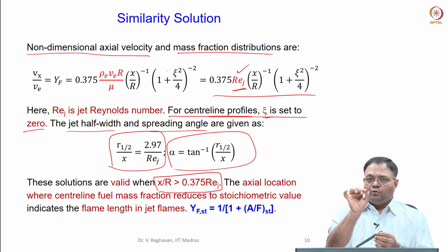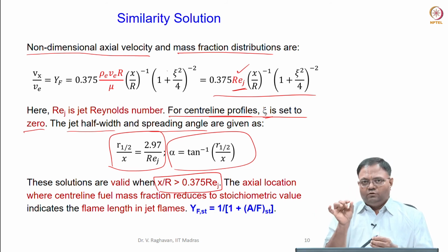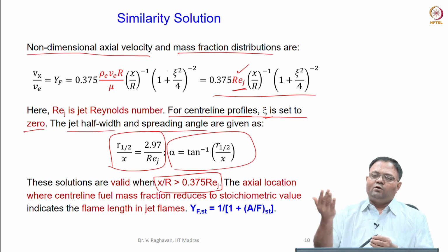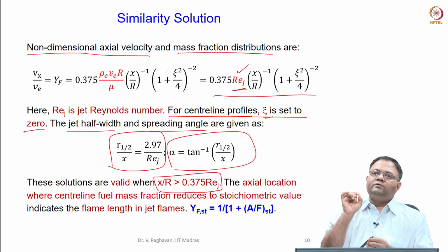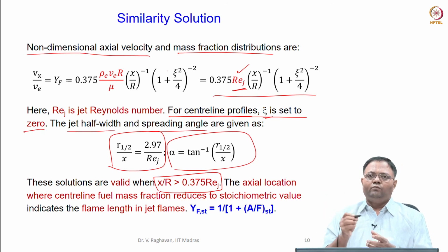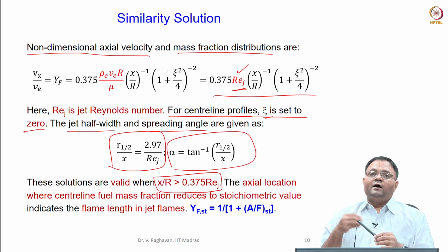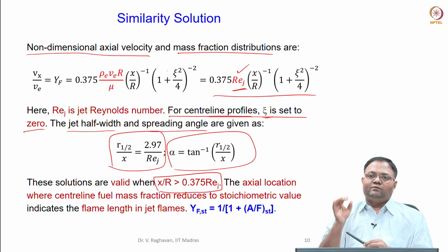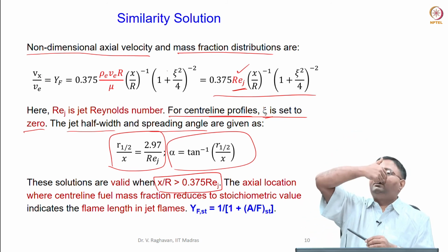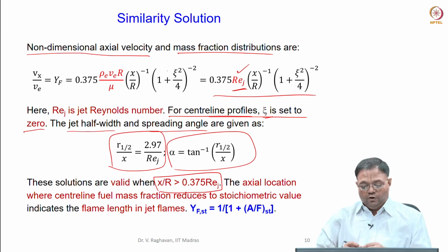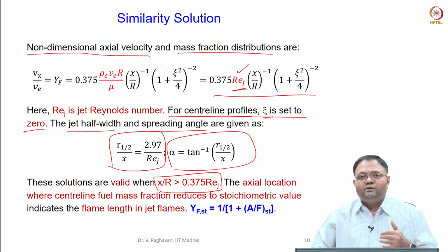So, when a fuel molecule travels from the central line to the jet edge, you can also see the oxygen diffusing in the radial direction towards the central line. At some point in the radius, the fuel molecule and the oxygen molecule will mix at stoichiometric proportions, where a flame zone will be formed upon ignition. That flame zone will be very thin. When you plot the locus of all this, you will see the flame surface basically. So, this is transport control.